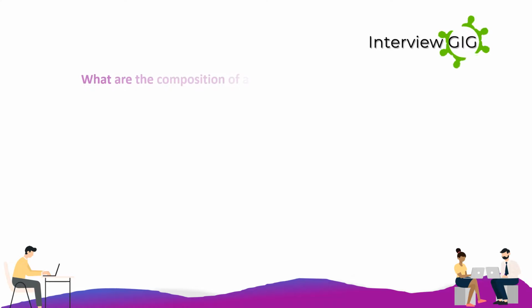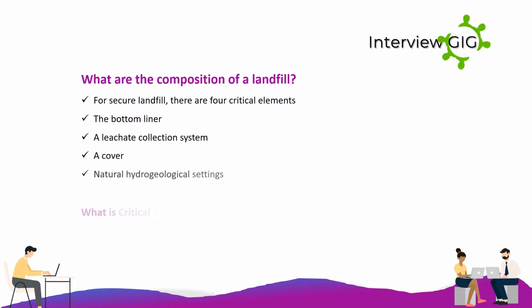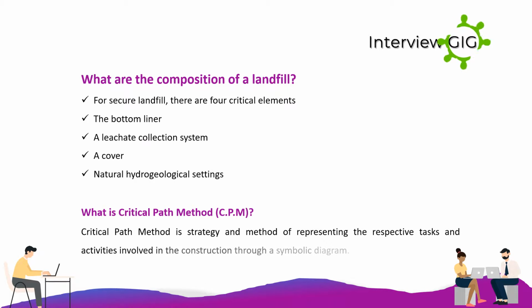What is the composition of a landfill? For a secure landfill, there are four critical elements: the bottom liner, a leachate collection system, a cover, natural hydrogeological settings.